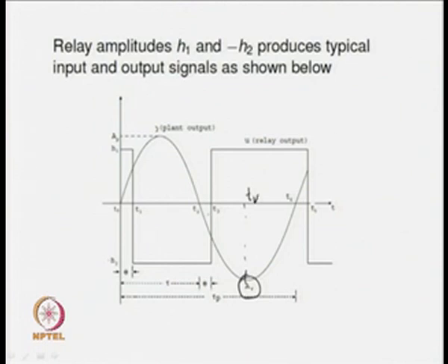The time Tv occurs after the range t minus tau minus theta, during which we have got the input to the system u(t minus tau minus theta) equal to plus h1. So, proper input is to be applied to obtain the negative peak of the sustained oscillatory output.